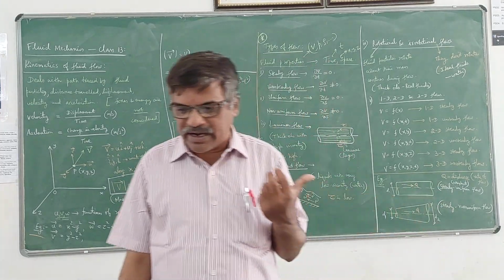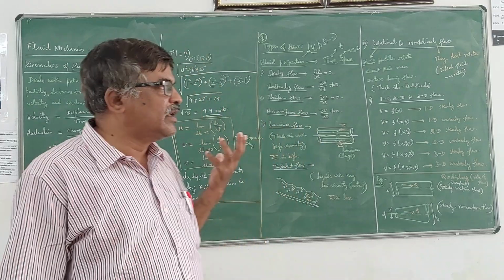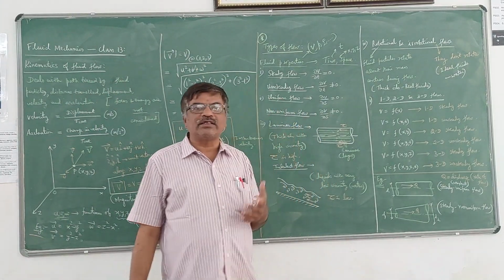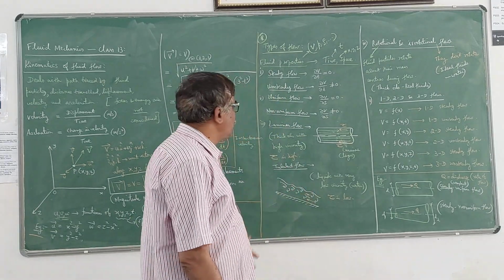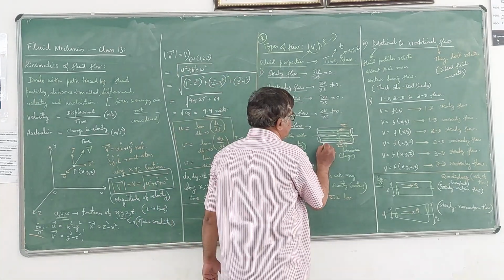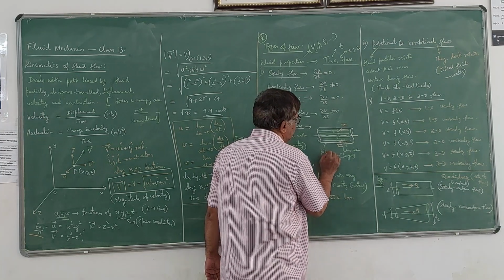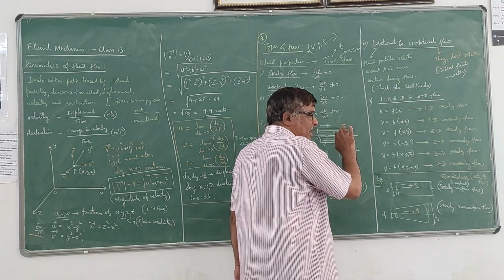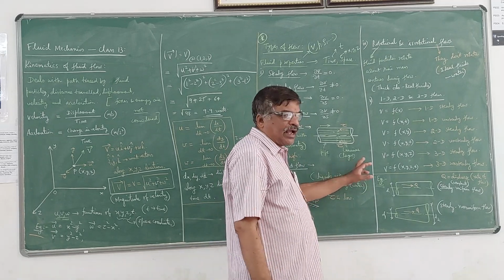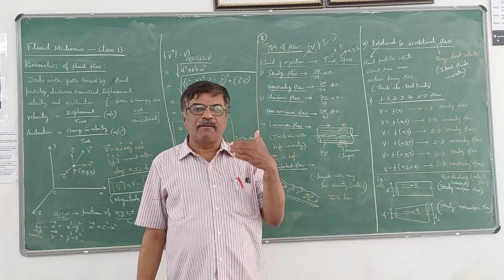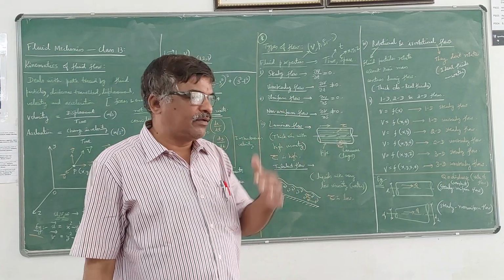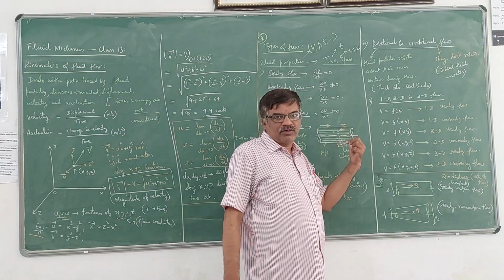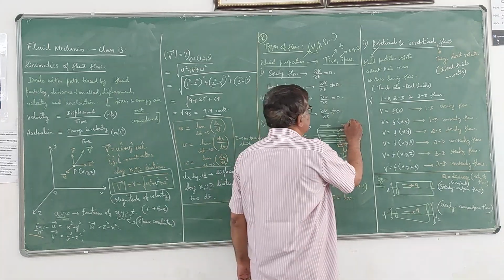This you have learnt in the first module, that is the first chapter, when I explained about Newton's law of viscosity. So I considered the flow as laminar flow. So laminar flow means, suppose if this is a pipe through which some liquid is flowing in this direction, and the flow takes place over laminae or layers, so that means one layer above the other. The meaning of that is it has got a high resistance to flow. So viscosity is very high, mu is very high.